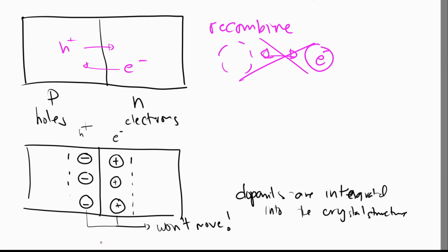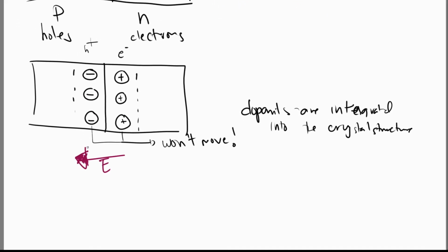So due to the production of charges at opposite sides of this junction, meron kang negative dito and positive dito, will actually form an electric field. Yes. We'll be forming an electric field due to this one. We call this your built-in electric field. And the presence of this electric field would then cause the drift of minority charge carriers. So this electric field would cause the drift of minority charge carriers.